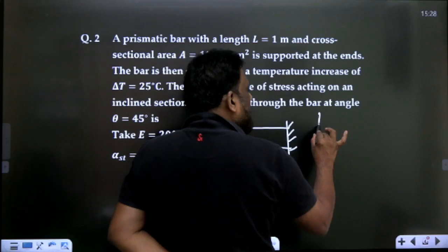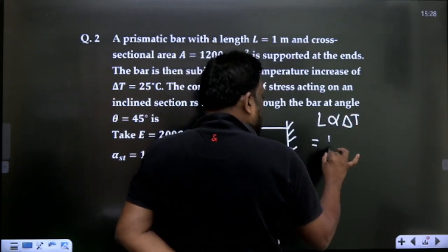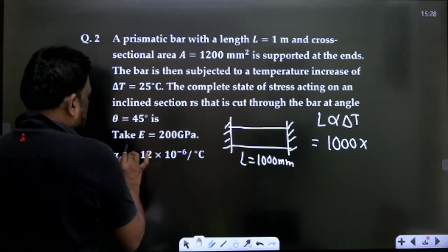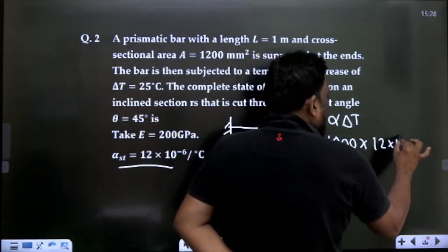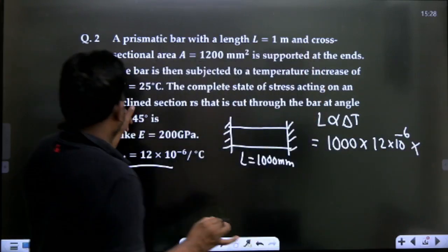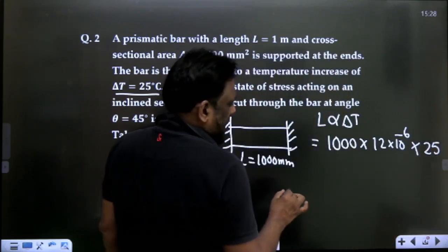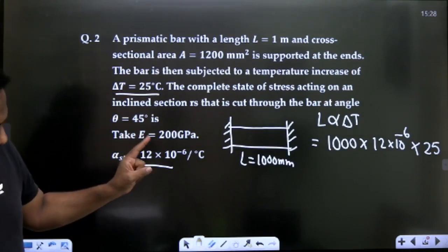The free expansion is given by L alpha delta T. The length is 1000 mm. Alpha is given. What is alpha, sir? 12 into 10 power minus 6. And delta T is given. What is delta T? It is 25. So how much value do you get? Let me check. How much is this? 1000 into 12 into...